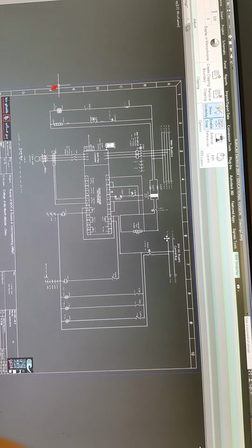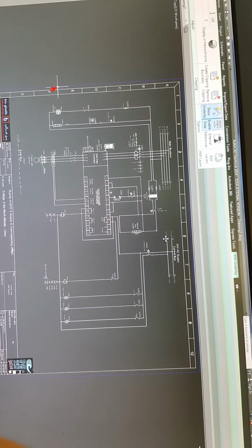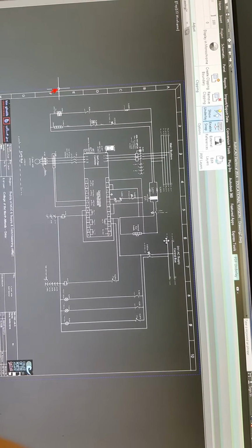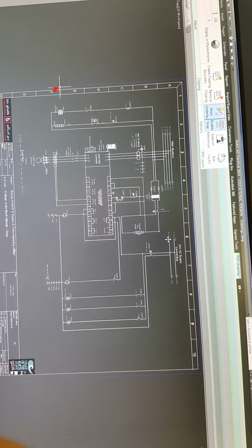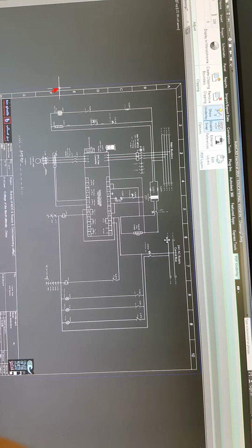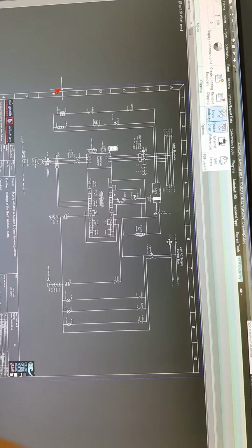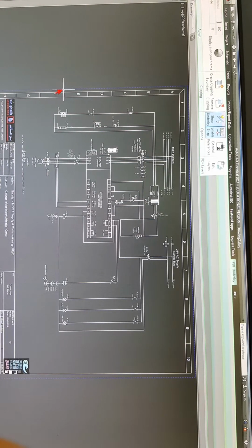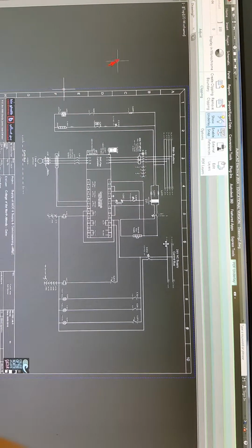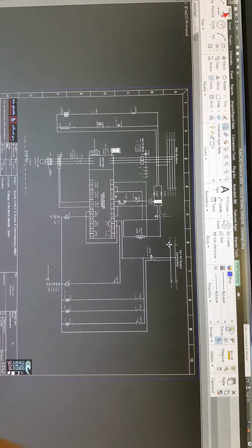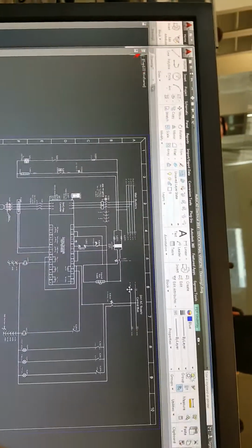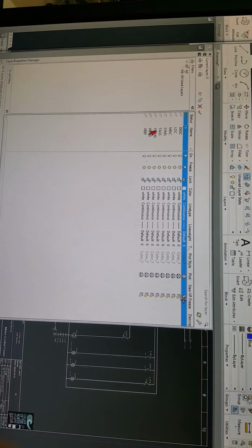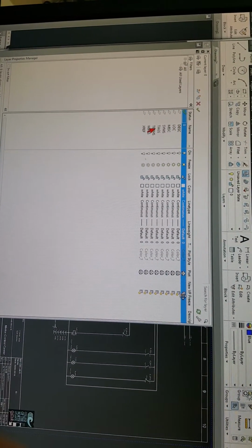But the advantage of using a layer is that you can turn the layer off, do some work, and then bring the layer back on without having to undo. So you're still making progress. For example, you'll see in a minute that some of the lines may not be perfectly horizontal, maybe a little bit slanted, so you need to clean them up. So let's go back to Home, go to Layer Properties, then create a new layer. Don't remove any of these existing layers. They have to do with the title block that you already have.